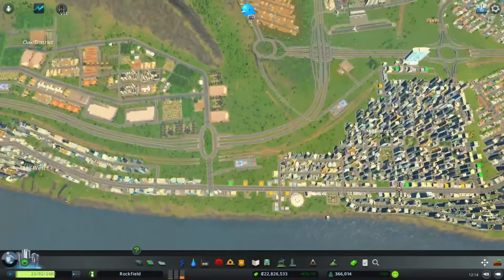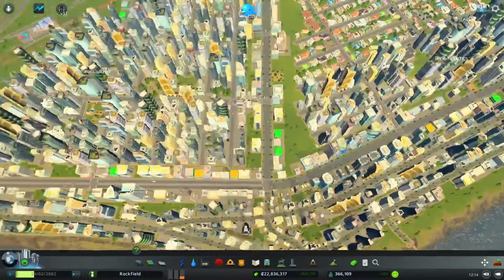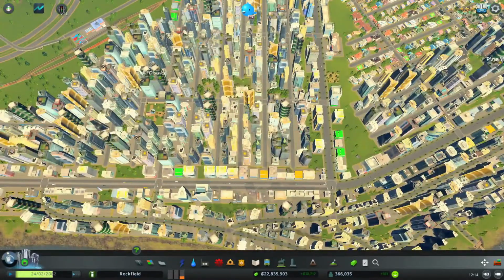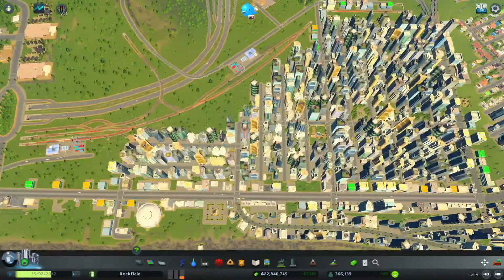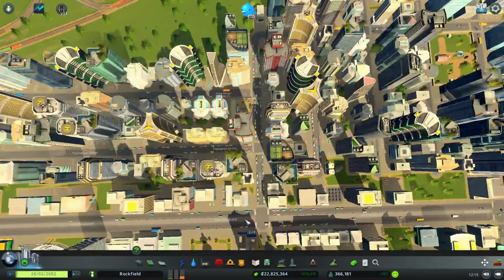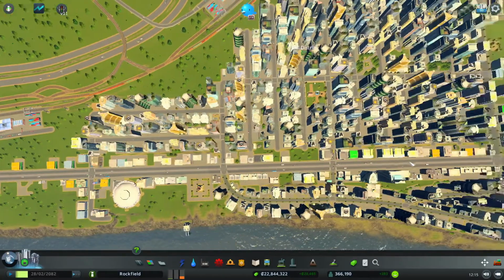When we have the highway exits, usually we have these main arterial roads that go through the city. None of the residential areas ever connect, or they shouldn't ever connect, to this arterial road. They go into these smaller collector roads, and then we zone around that. That way, if anyone wants to go from a residence onto a big road, they have to first go onto these collectors, which allows people to go a bit slower. Because imagine if you're turning, you're slowing down things a bit. And you don't want people coming in and out directly onto these arterial roads, because that would slow down traffic a lot. These are meant for fast traffic, through traffic for the most part.